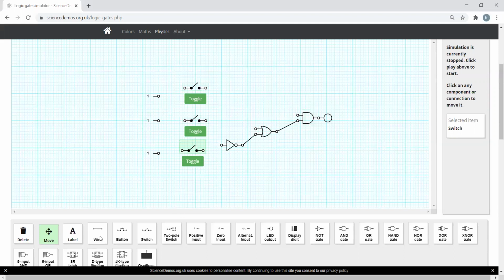So what happens in the model is it says the master switch needs to be on. So that's going to be one of the conditions we have going into the AND gate. This top switch is going to represent the master switch. And I've just slightly missed that there, so I'm going to go back to move. I'll delete that wire, I can't quite join it up. So go into new wire tool, and from the circle there, I'll join this up. So this is our master switch here.